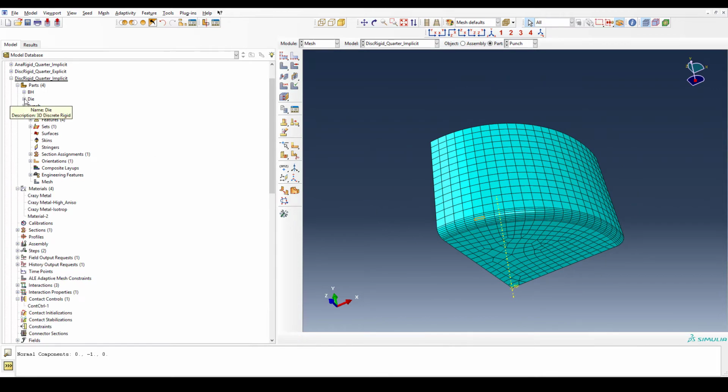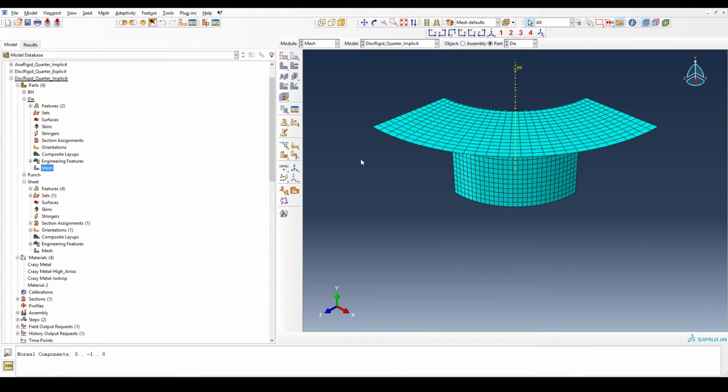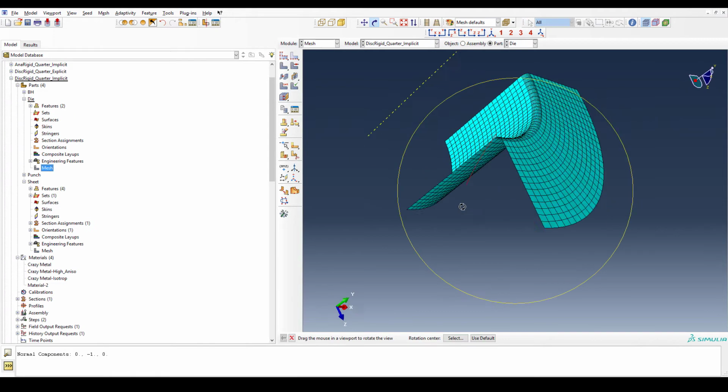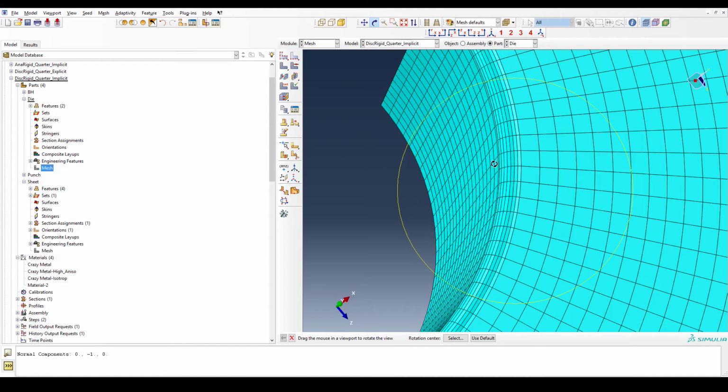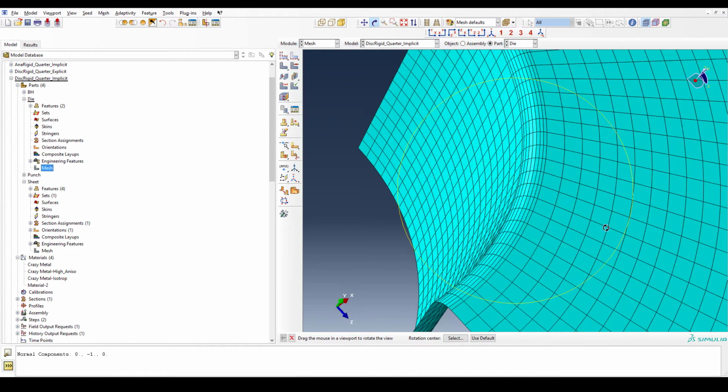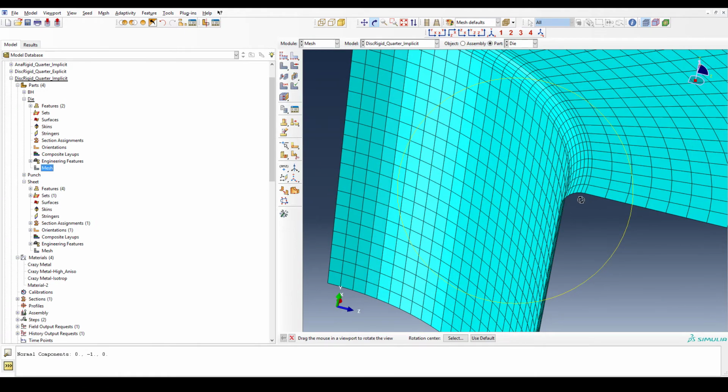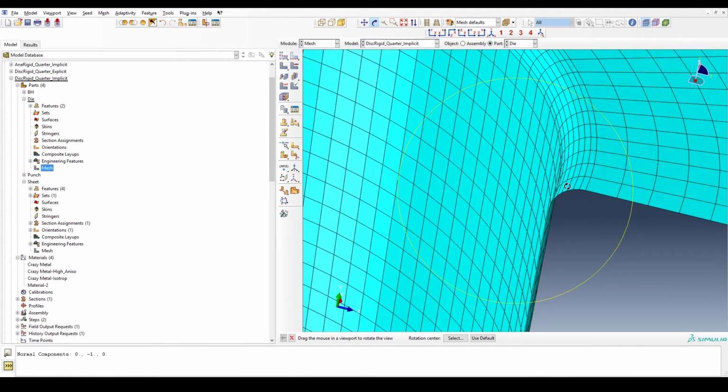The same, or even more so, applies to the die or the matrix. You can see again the meshing here, especially since it's an inner radius that's being meshed, and this will definitely have a big impact on your results. So always keep that in mind. I would say never go below 5 or even 7.